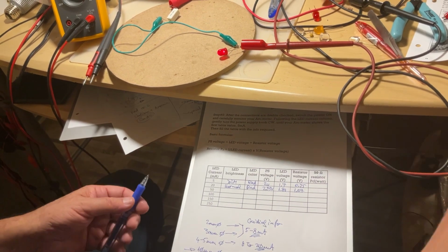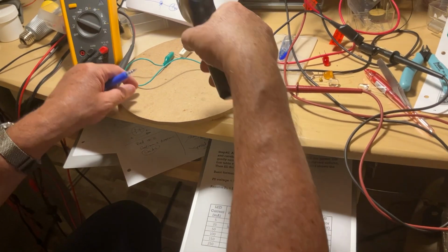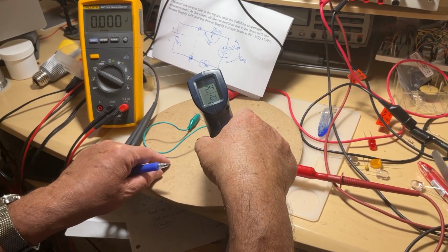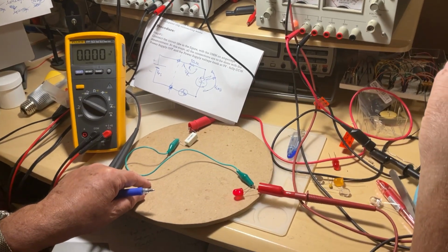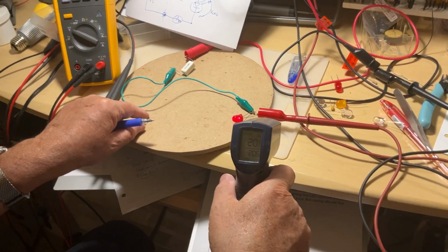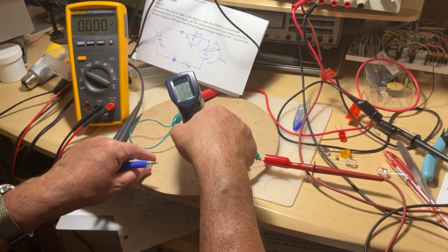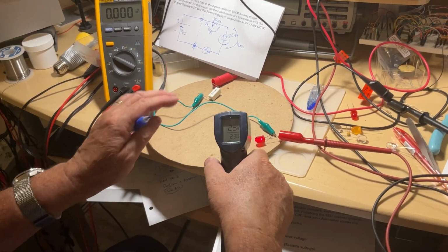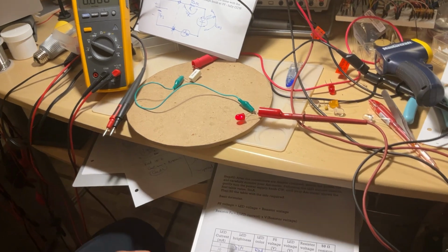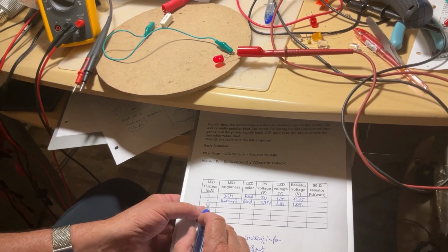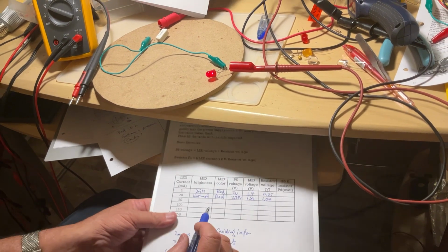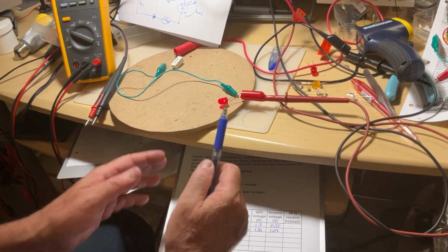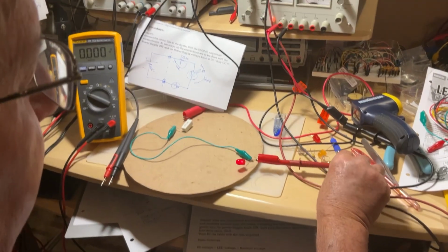And the temperature, I can measure the temperature of the limiting resistor. It's exactly the room temperature. If I measure the room temperature anywhere, it's 20 Celsius degrees in the room. This one is 23.8. So it's just a bit warm, okay? So it's a normal temperature. But we go further. We increase the current into the LED to 50 milliamps. And as soon as you do this, you have to take the measurements relatively quickly. So now I'm going to talk less and take the measurements quickly, because otherwise I can damage the diode. Okay.